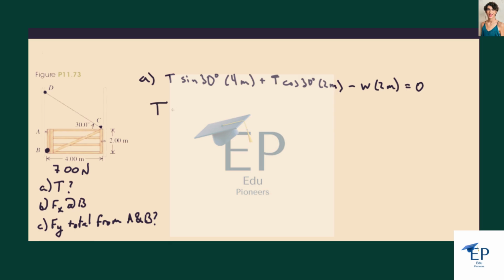So we just solve this for the magnitude of the tension. And it's going to be W over 2 sine, just save ourselves some writing and call it theta, so 30 degrees, plus the cosine of theta. Plug in the numbers, and this is 375 newtons.